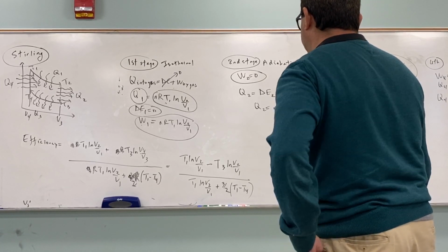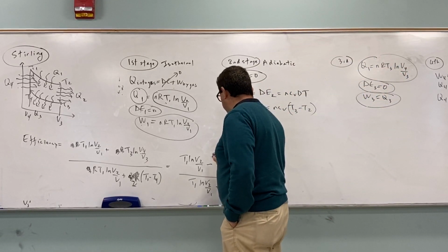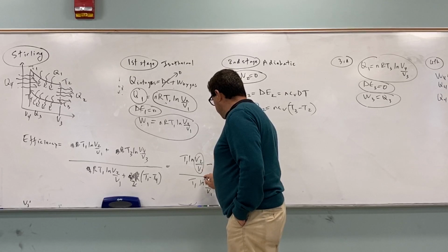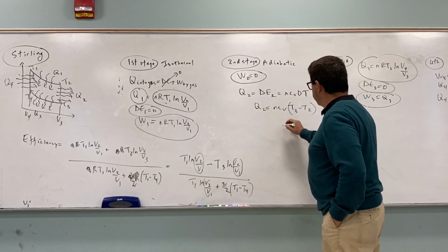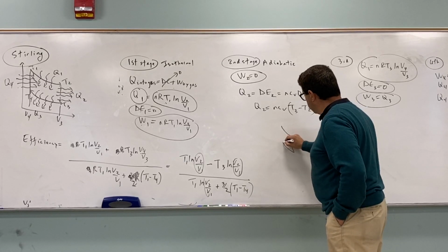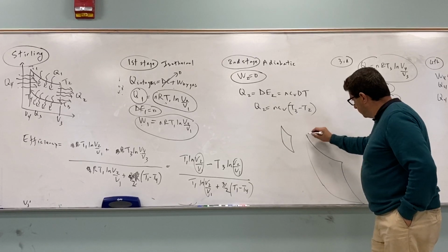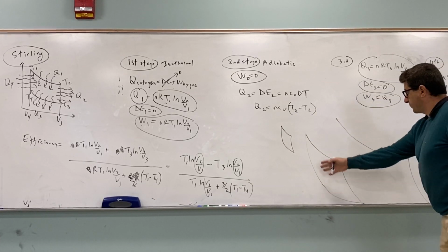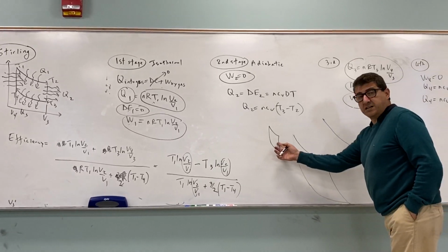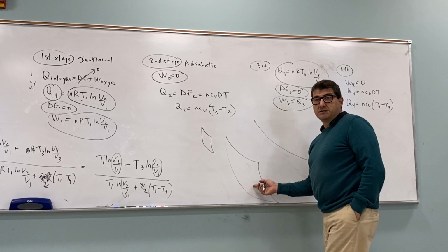It seems like on a Stirling engine, the efficiency depends quite highly on the ratio of the volumes, whereas in the Carnot cycle, it doesn't really matter. You could have something like this, bigger, or something like this, huge. Of course, this would do more work than this, but you would have to put more heat into this guy.